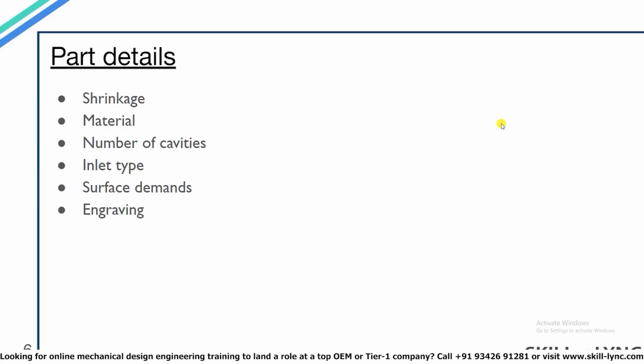For example, if you're watching this video on a PC, then you probably have a keyboard in front of you, right? Now, if you open your keyboard, then you will find many plastic parts inside it. Since these parts are not visible from outside, it doesn't matter what surface finish they have. Adding good surface finish requires additional cost and time and must be avoided where it's not necessary. Also, the type of surface finish required will also affect the draft angle given for the geometry.